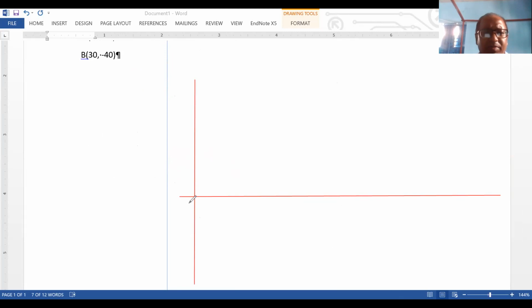Now you write down: this is 0. From here, going to the left side, this is sigma, but it is negative sigma. And on the right side, this sigma is positive sigma. And tau in the upward direction, if it's clockwise, then it is positive. And at the bottom is negative tau. I'd say this is minus tau.